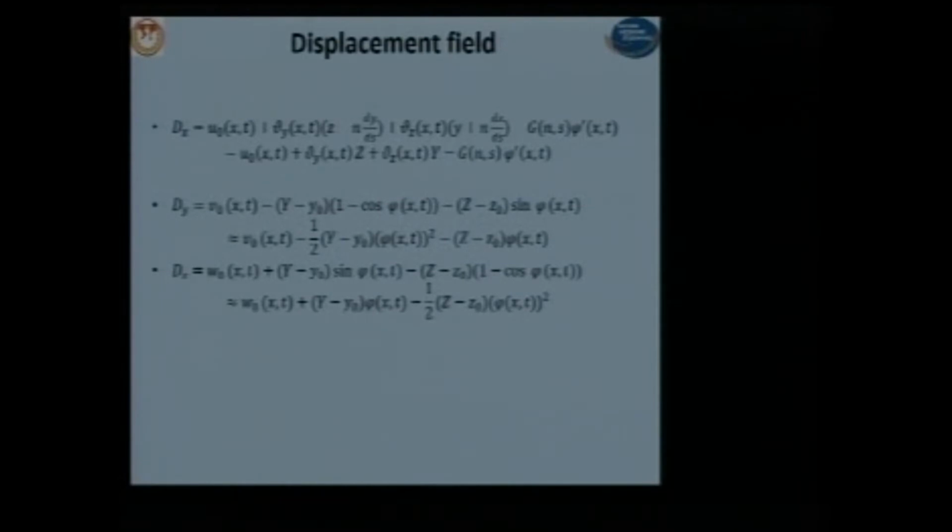What is important in this is that we have to include some nonlinear terms. They are important. In a rotating structure, there are some cosine and sine functions. If we approximate, for example, this cosine, keeping perturbation orders, and we take only the first term as 1, then we neglect very important terms.